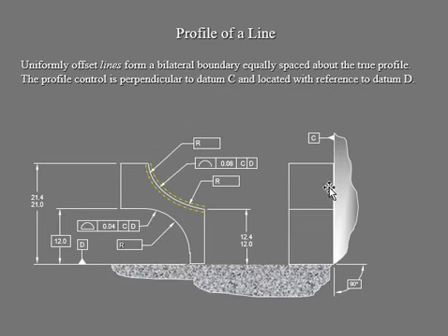Now we're going to gauge it. So put the gauge, do a touch point. Your C is a primary, so 3 touch point. Your D is a secondary, so you have a 2 touch point to the highest point, yeah? So we can see the datum plane right there and right here. And they are, of course, 90 degree to the surface.